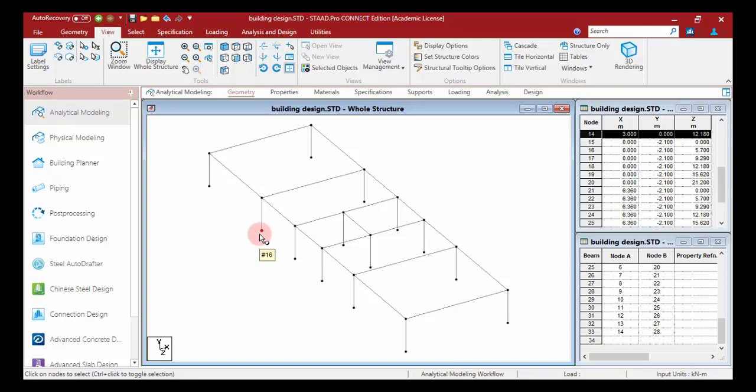Here you see this is the plinth level, and below plinth level these columns are going up till the foundation level. Now let us create a column and beam up to first floor level, because after first floor level the beam layout is going to be same for the second floor level and for the third floor level also. So for doing that, what I will do, I will view the plinth level again.